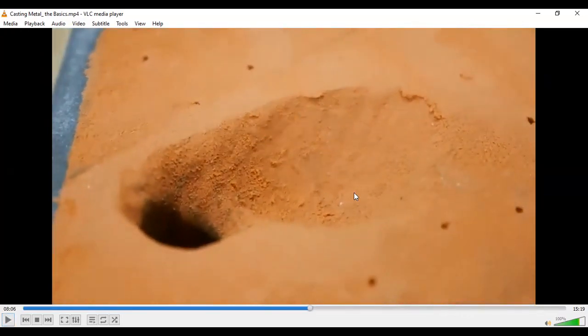Right, that pouring basin is what is responsible for making the molten metal flow easily. Otherwise, if you pour it directly, it will come down and there will be erosion at the bottom where you have the L type of portion, from the sprue to the other part of the gating system. So to avoid that, we are giving this pouring basin. You'll pour it here and it will slowly come down through the sprue.